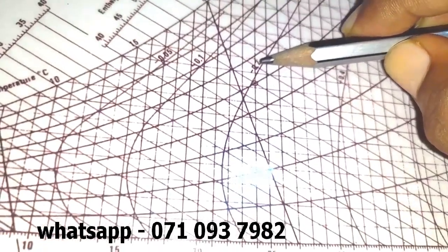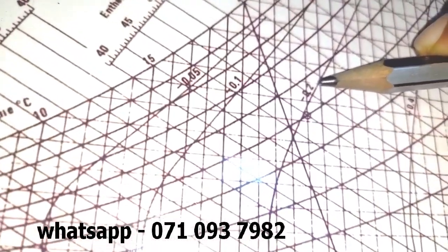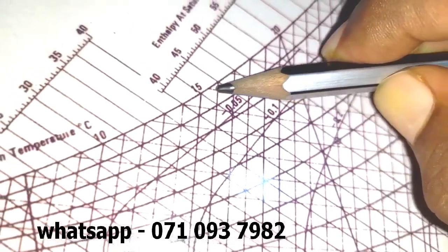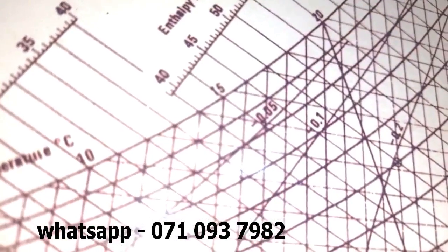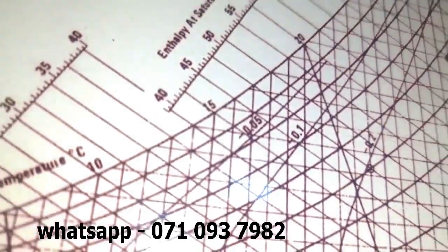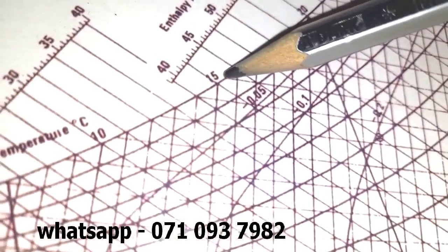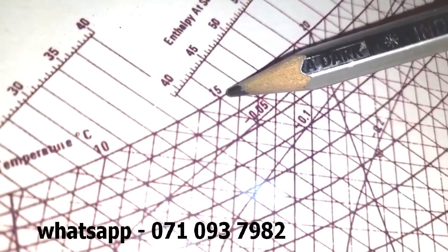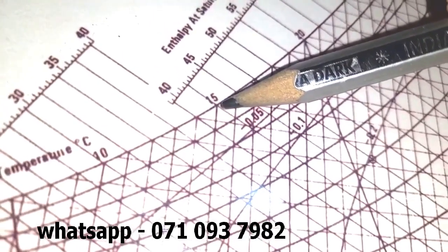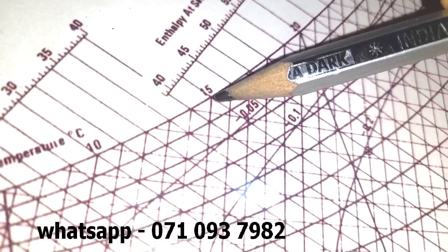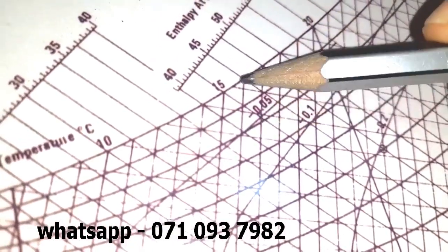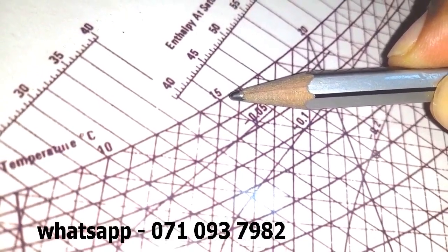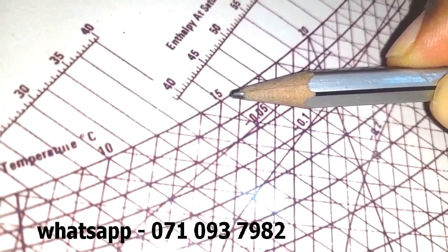Here, so now this is the intersection. Now follow this and project this point of intersection, and it will direct you to here. Now carefully focus on this point. Be very careful, that will direct you to here. So now from this curve you can read the dew point temperature. Actually, when reading the dew point temperature, you are going to read it from the wet bulb temperature scale. Got it? So this is the point of intersection when the previous point of intersection is projected until it touches the 100% relative humidity line.